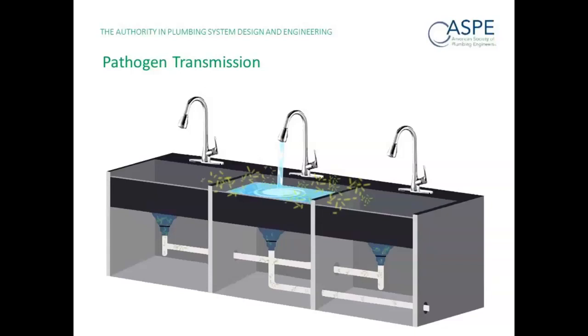I see that there are many, many plumbing designers on this call right now. So as you're aware, and I've seen a lot more of this, that they have moved the drain location from the center of the sinks. They're now in the back corner for this very reason. What happens is the microbes start growing in the P-trap of the drain, and these things can grow up to about 5 millimeters per day and spread from P-trap to P-trap to P-trap down a waistline. And what happens is when you dispose of water or any fluid down the drain, it aerosolizes the bacteria that's in the drain and it splashes, similar to what we've seen with the water closets when they flush and then the air kind of spreads it and disperses the pathogens throughout the room.